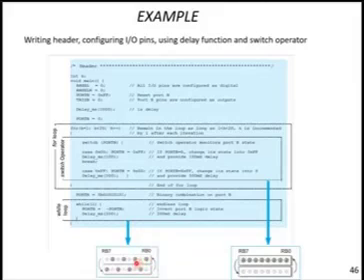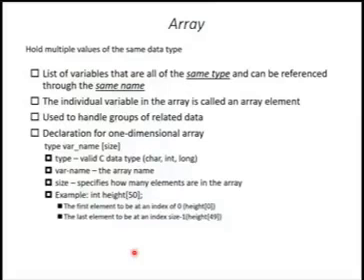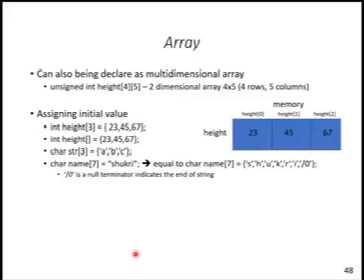Then for port B, we delete any initial value in port B, we reset the port B value, and then we use a for loop. Any program we want to execute, we put it inside the for loop, and then we also have switch case. If the switch on port B is true, then all bits of port B become true.